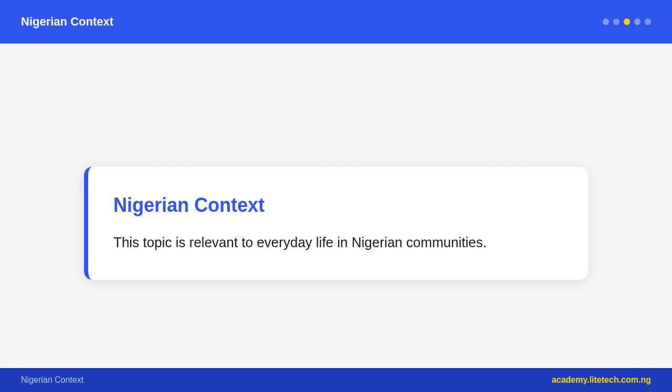A. V0 equals VRMS times square root 2 is equal to 240 times 1.414 equals 339.4 V, which is almost equal to 339 V. B. Peak-to-peak voltage equals 2 times V0 is equal to 2 times 339 equals 678 V.